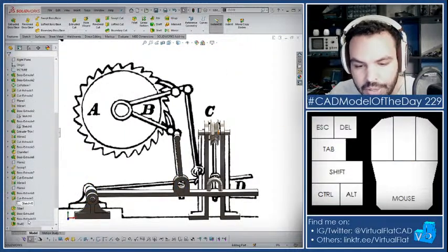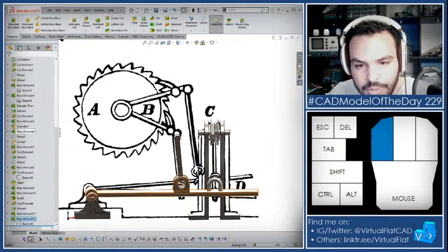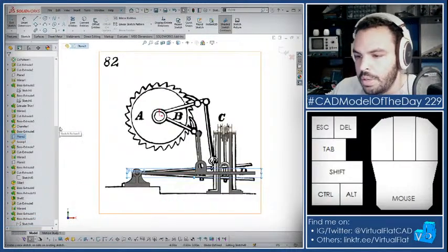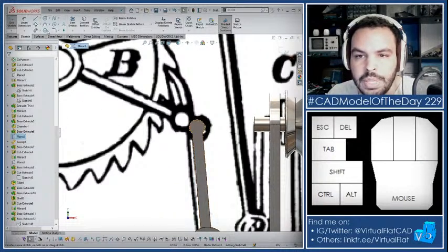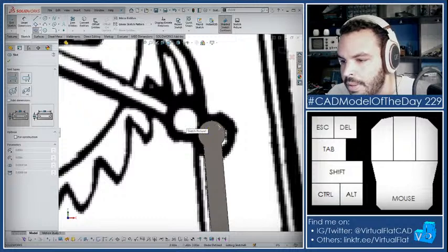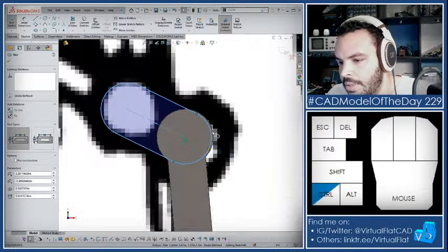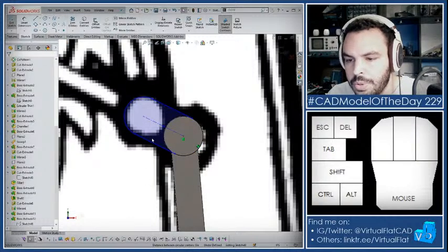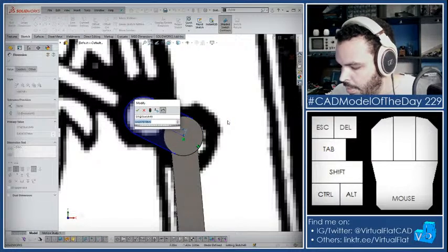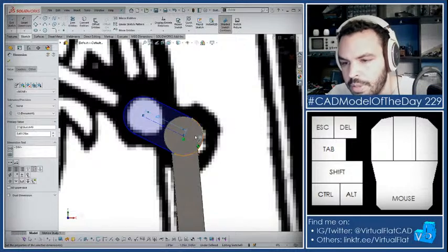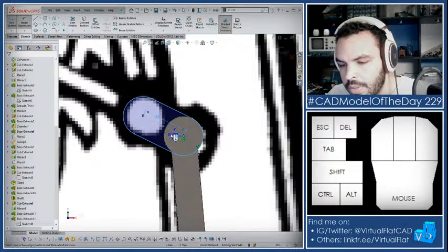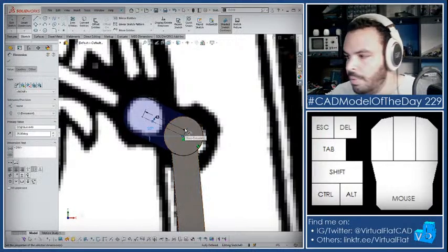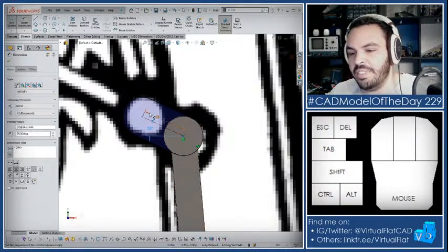So let's see. Let's just make another link. We're just gonna try and assemble this 4-bar mechanism. So yet another sketch. I might make this simply a straight slot, from here to here, and say that and that co-radial. That wants to be a certain angle, it would appear. Well, actually, let's get its length first. 0.43125. Looks like that's sitting right at 25 degrees.